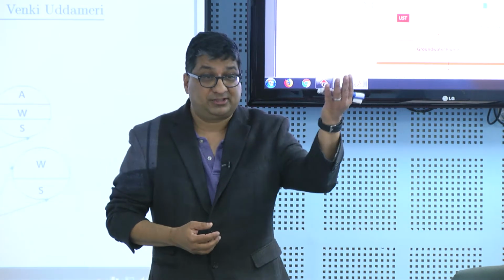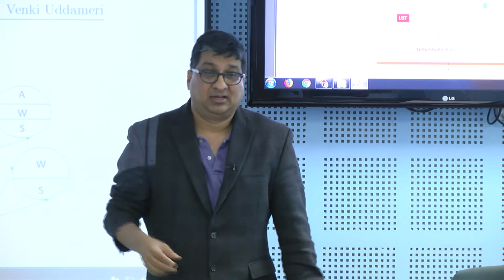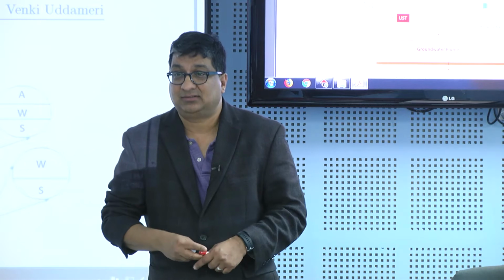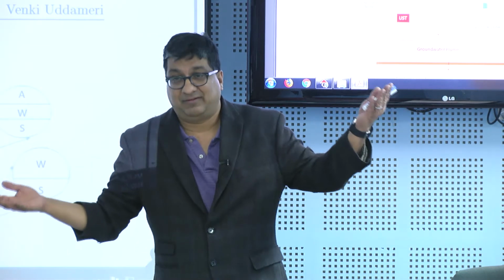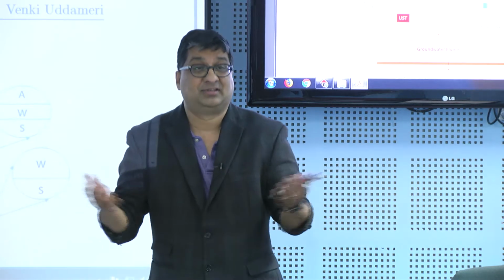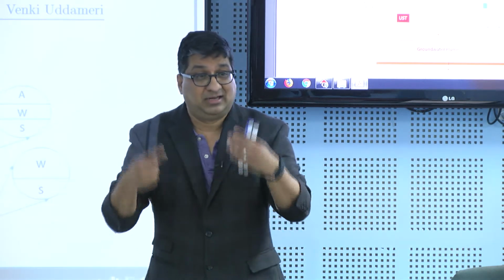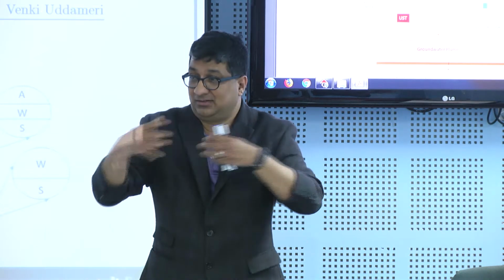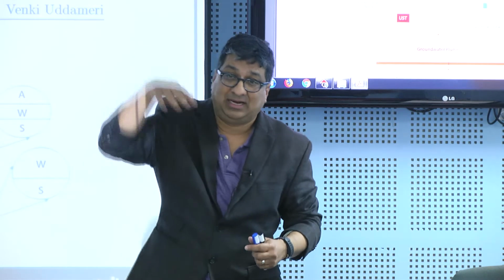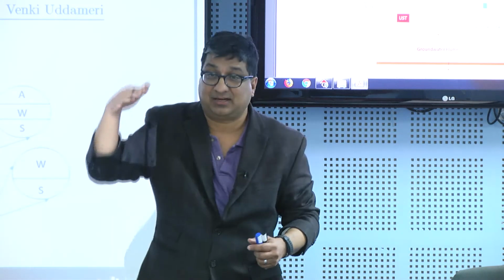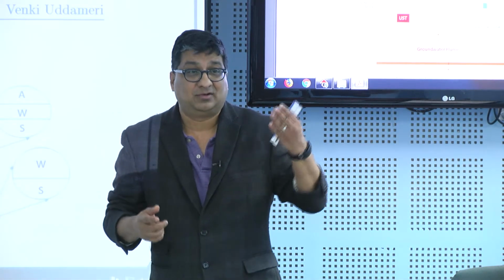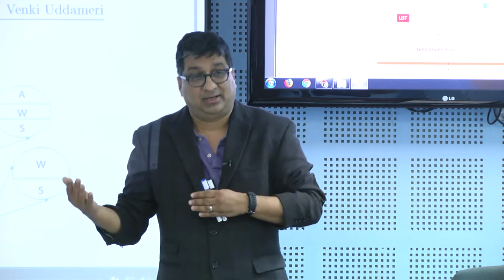If I take just static water sitting in a glass and put a drop of ink in it, it will eventually become blue. That's diffusion, basically. Dispersion is diffusion on steroids. There is mixing going on. If I mix it, the movement is a little bit more. And because the water is moving through pores, it takes a very tortuous path, and because it's taking a tortuous path, it tends to get mixed. But that mixing is not complete.